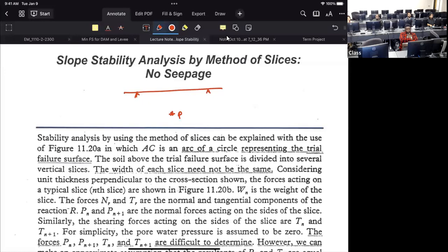Boussinesq's theory, practically. What is earth pressure? Boussinesq's formula is a different thing. Boussinesq's formula gives you the stress increase. That's not for your earth pressure. You build a building, you put additional stress on top of it. How that additional stress will be distributed through the soil is explained by the Boussinesq theory, not the earth pressure. Earth pressure is like gravity.